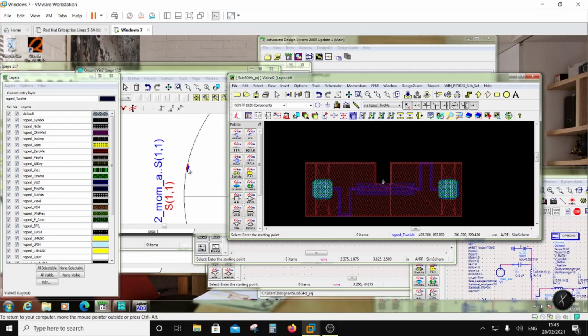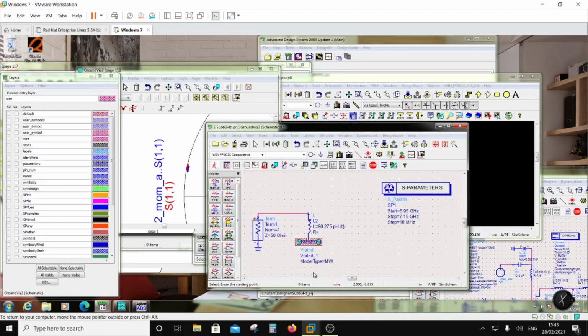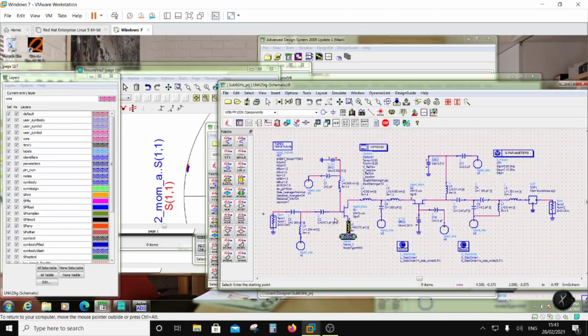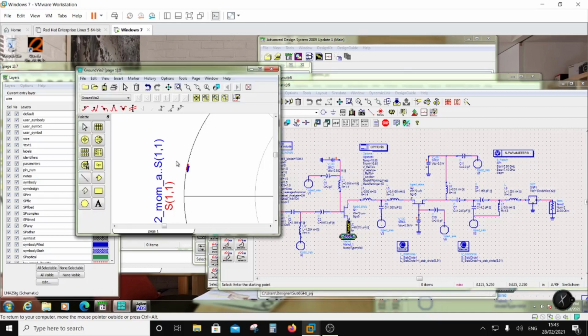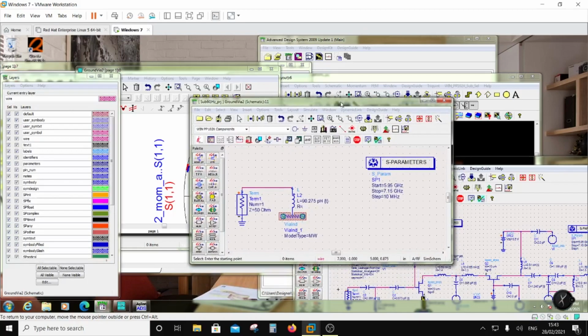So once I do that, they are almost there. Now why this is important is because this inductance decides both the interstage impedance as well as the input impedance. So as to have that same as in the circuit, I have to match these two. So once I do that, then I can go ahead and run the simulation from 0 to 40.